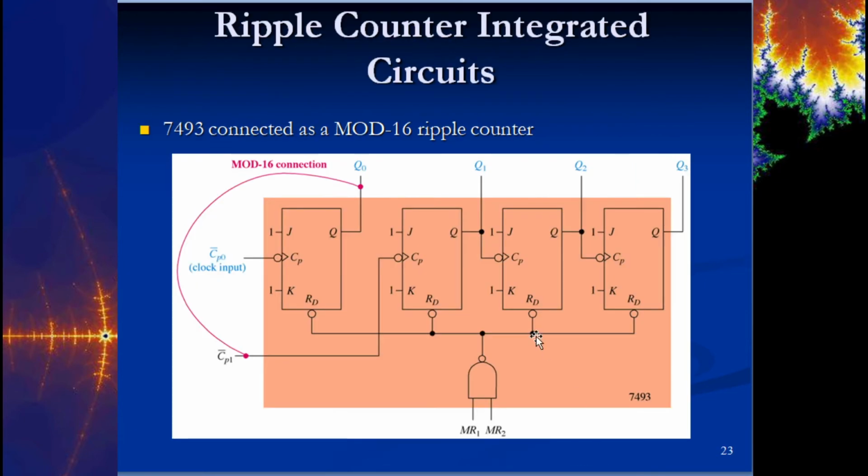All right. So if you wanted a way to manually reset this, you would have to set up some external circuitry here to make that happen. Maybe what you do is tie one of these always high, and then have the output of an OR on the other side, right? Because then the AND gate is really being controlled by the OR, okay? But anyway, this is great if you need to have a hex counter. For some reason, if you want your 7-segment display to count from 0 to 9 and then from A to F or A to E, you can do that as well.